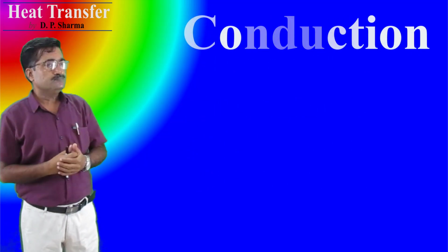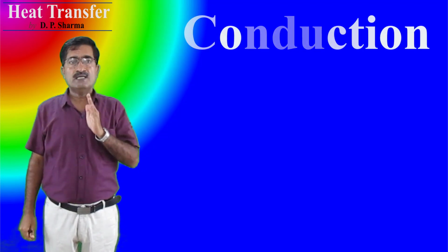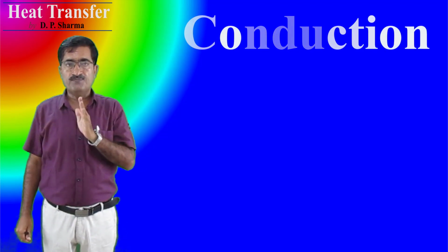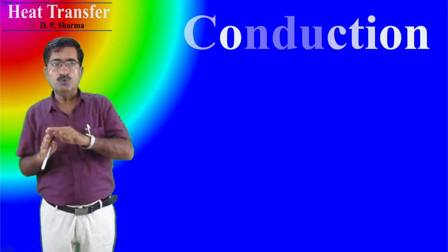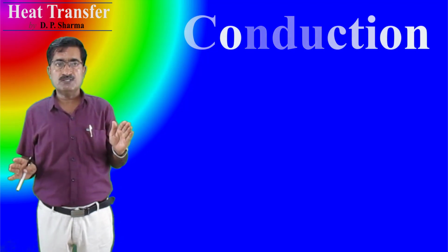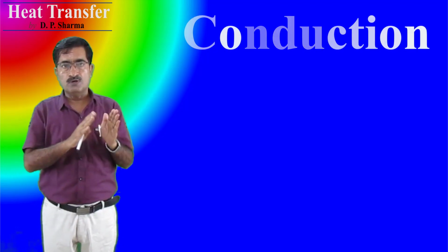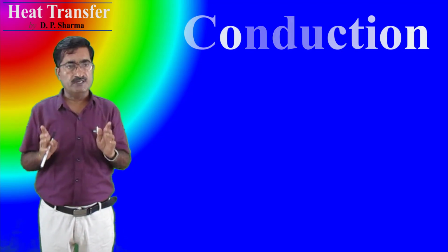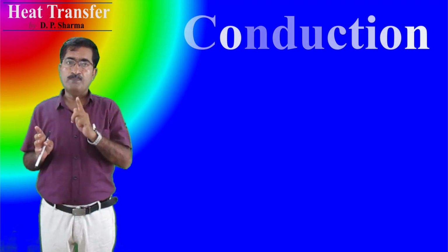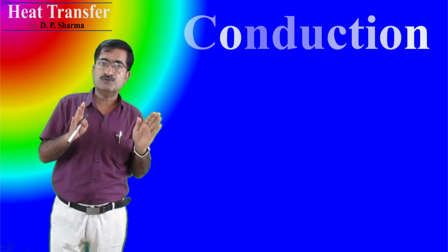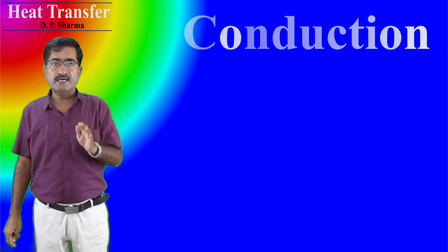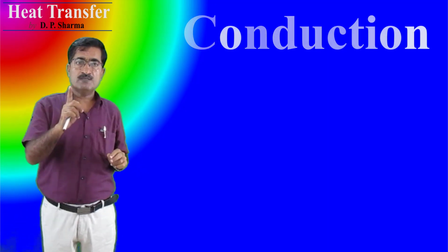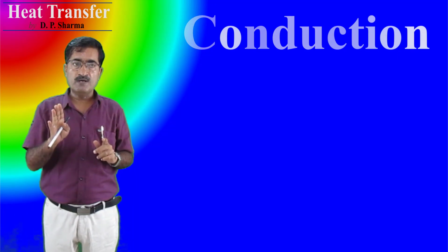Now, conduction. Conduction is the transfer of heat from one part of substance to another part of same substance or from one substance to another in physical contact with it without an appreciable displacement of molecules forming the substance. In solid, the heat is conducted by two mechanisms. First, by lattice vibration, this is major part. Second, by transport of free electrons.